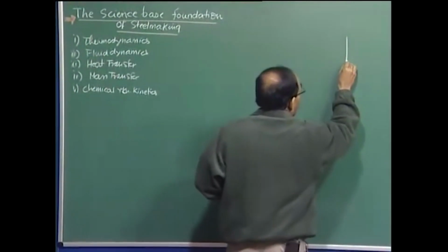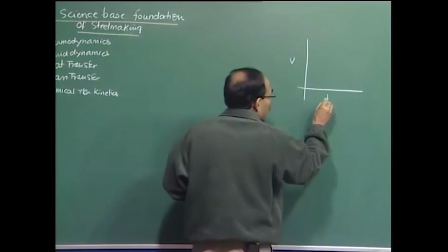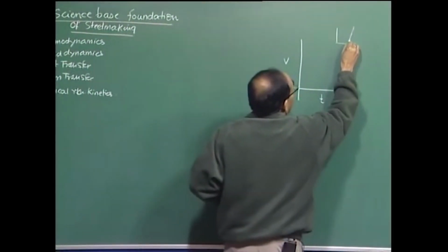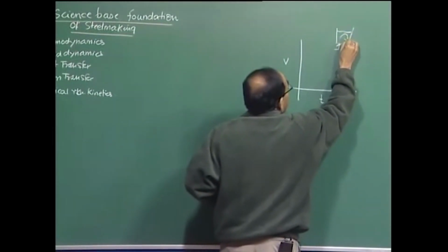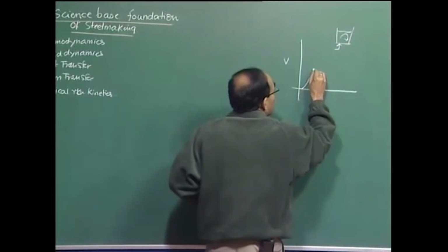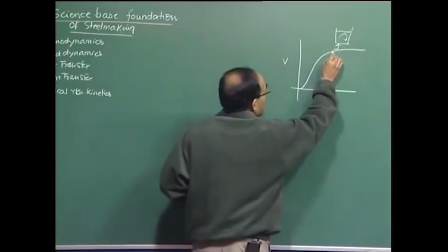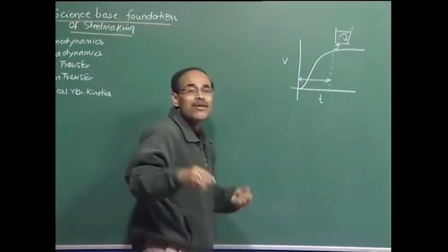So, for example, if you plot velocity at a location versus time with gas injection in a ladle, a small little figure I draw. So, I introduce a gas here, and then the flow develops, and you see the flow goes something like this. So, this is basically the period which is called the flow establishment period or the period of transience.